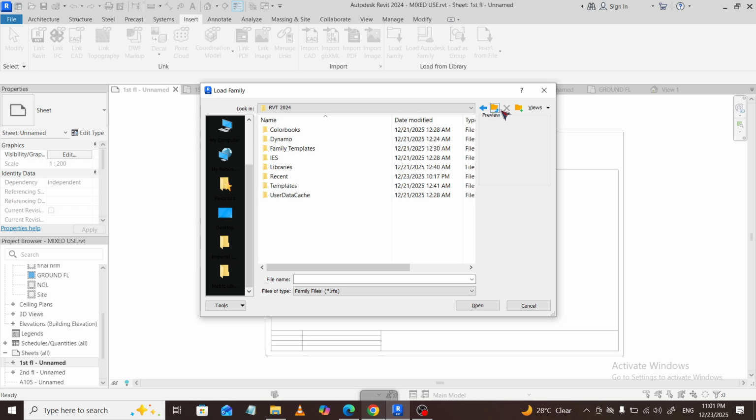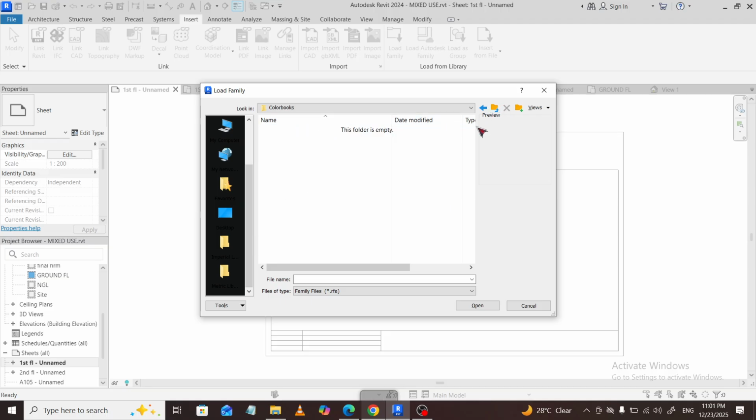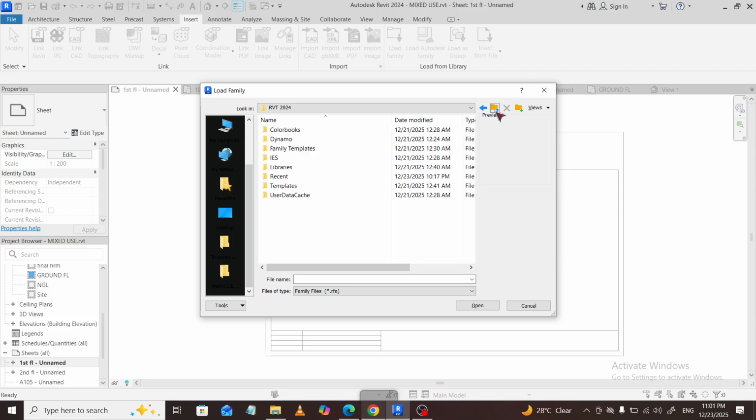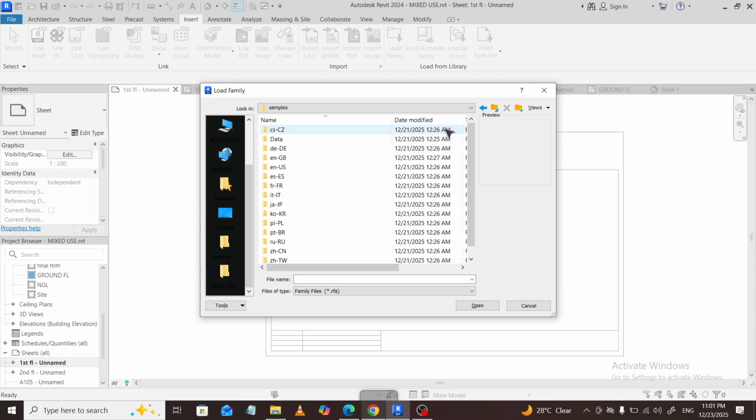Since the North Arrow is typically tied to True North for geographic accuracy, use existing geometry, grid lines, or title block elements as visual guides to keep the symbol neatly aligned. If you need fine control, temporarily zoom in or use temporary dimensions and reference lines to snap accurately.